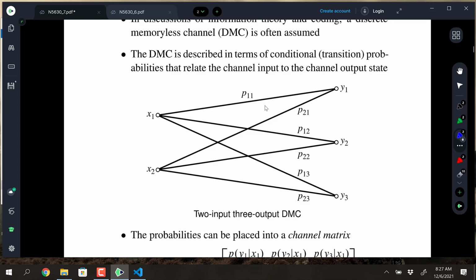So the way I would think of it, from an information theory standpoint, is y1 is x1, it's a hard value. y2 is a gray value, in that we don't know whether it's a type 1 or a type 2, and then y3 is the type 2. That's sort of a typical application where we have a soft value in the middle. So we have two certain values, and then we're going to just draw another conclusion saying we don't know, and we might carry that along and then use that in coding, because that's what we're going to be talking about too, soft decision decoding, where you don't make hard decisions right away. You try to put together a bunch of soft information and then finally make an assessment.